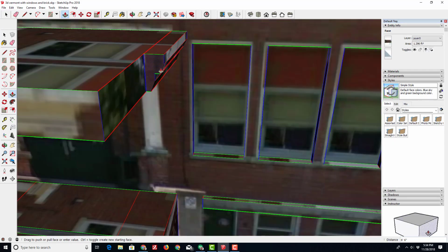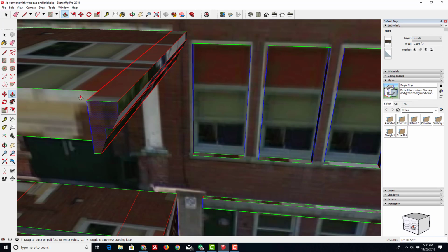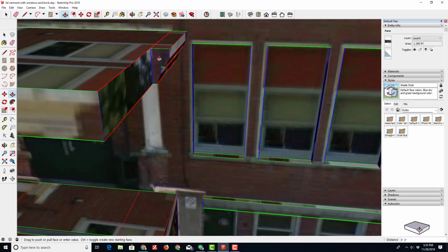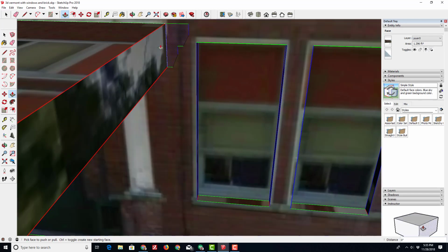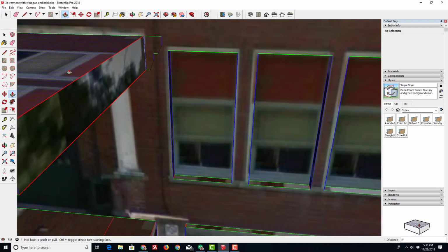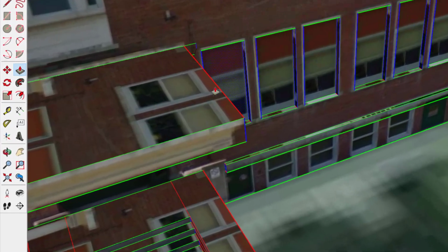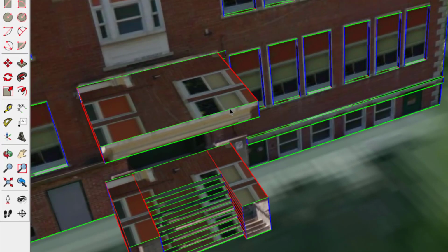So now that we've got our cool design made, if we used push-pull, we could pull it out, but we'd have to do something for this corner in the front. So that's why Trimble has created the awesome Follow Me tool. When you click Follow Me, it's going to trace whatever section you pick. Well, we need to pick a special section where we're just using these 3 lines out here.